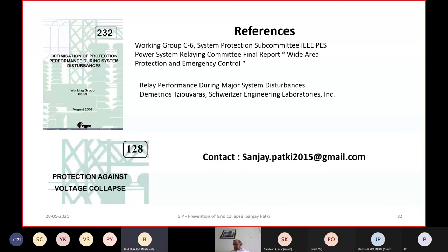Sir, transformers generally they don't give any negative sequence protection. Yeah, that's why I said unbalanced current detection is normally there. Normally we do it in the SCADA system, including for transformers. It's not a negative sequence protection, but it just detects the current unbalance.